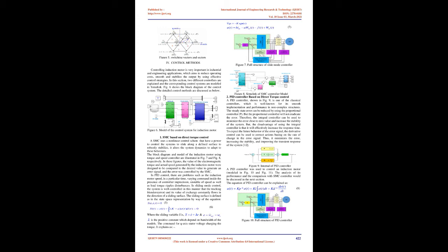Modeling of 3-phase induction motor. The three-phase induction motor is modeled in state space representation in equation 1. The models of the induction motor in rotor and stator frames are explained in 9. The induction motor stator current is written as a vector in the dq axis. The d-axis is used to manipulate the rotor flux and the q-axis is to control output torque. In other words, torque and flux are space vectors.